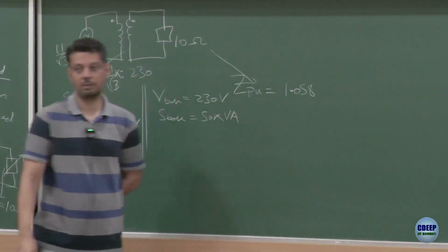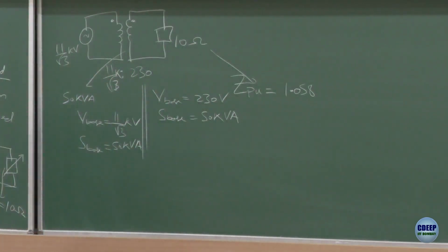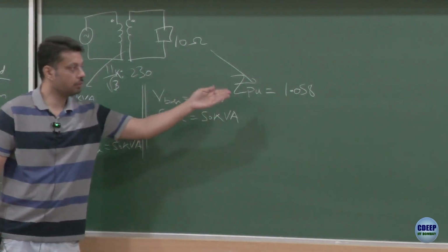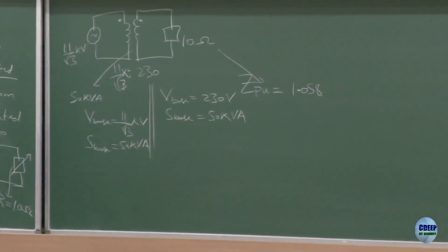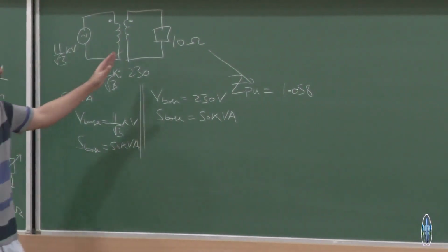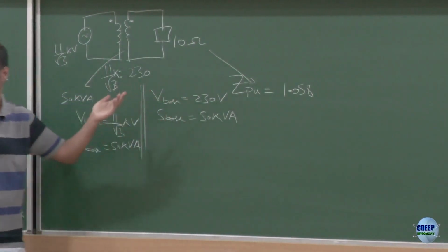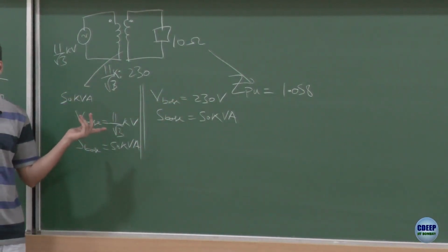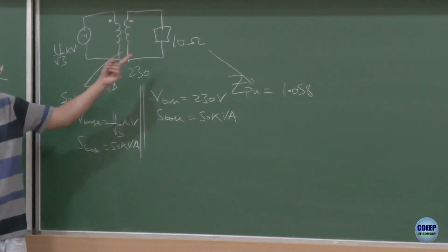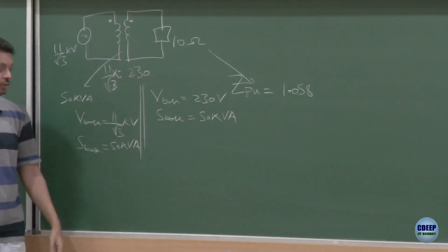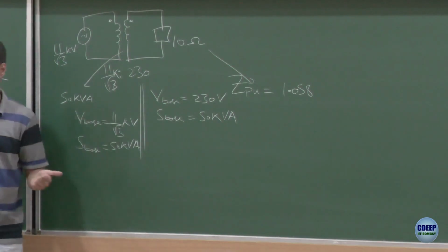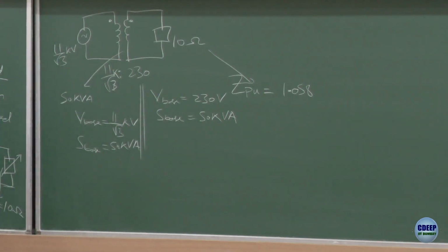There are no imaginary components. It's R in per unit. Is this matching? Okay. So this is ZPU. Generally, you would not expect ZPU to be more than 1. Why? Because if it's more than 1, that implies that the power this load is drawing is more than the rated power, right? So if you calculate the power it is drawing, it is voltage 230 squared by 10, which would come out to be more than 50 kVA, right?